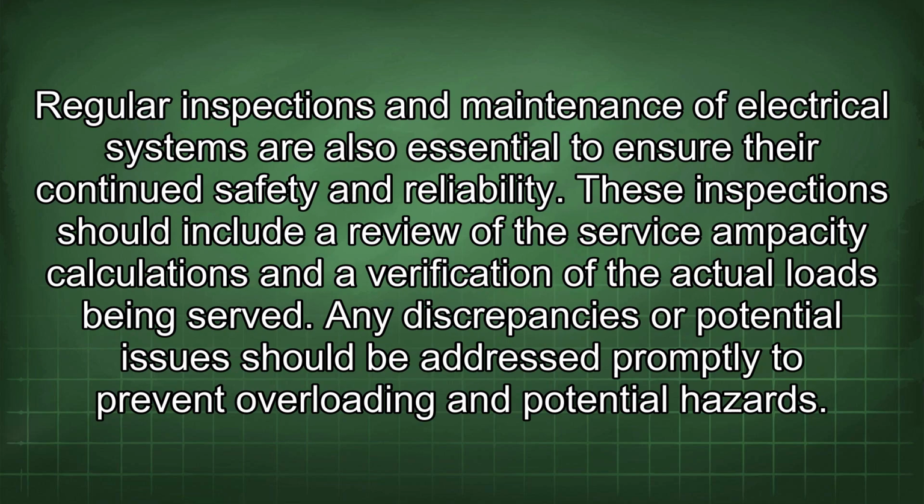Regular inspections and maintenance of electrical systems are also essential to ensure their continued safety and reliability. These inspections should include a review of the service ampacity calculations and a verification of the actual loads being served. Any discrepancies or potential issues should be addressed promptly to prevent overloading and potential hazards.